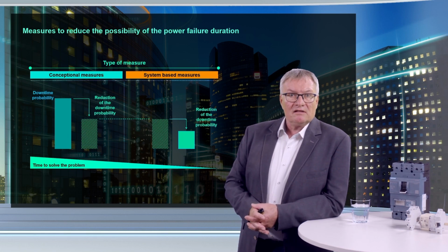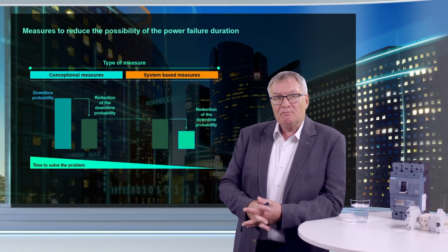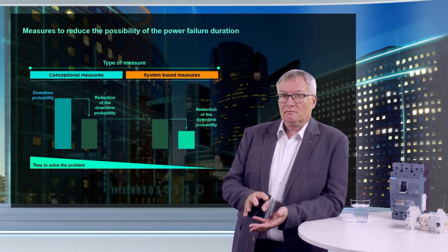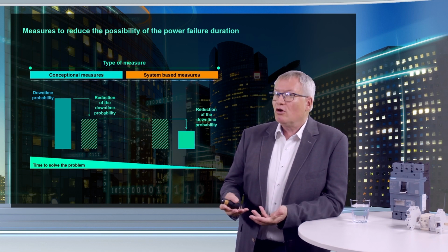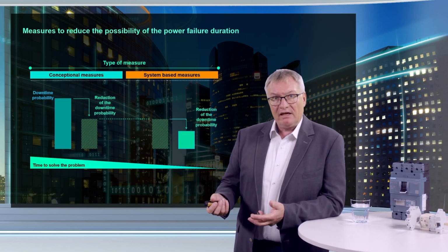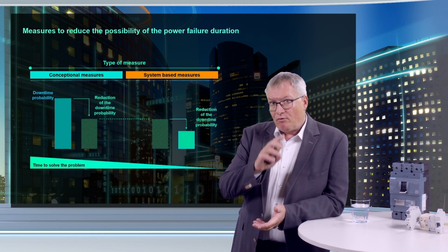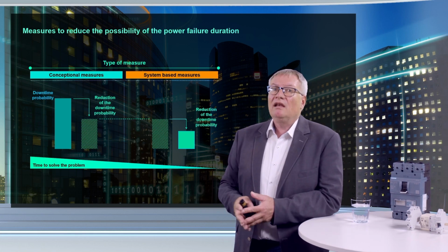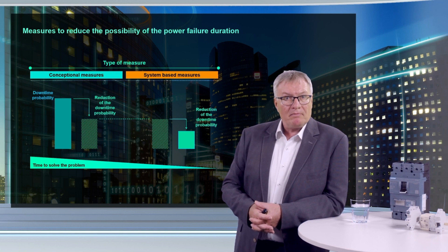With devices or systems in withdrawable technology, plug-in technology or modular systems, cost and space incentives over capacities can be reduced to an acceptable level. Although sophisticated withdrawable technology concepts do not prevent failures, they ensure that a system can be put back into operation thanks to a fast response time. They promote availability through safe operation and fast interchangeability in the event of a malfunction. However, this requires locally available spare parts supply.